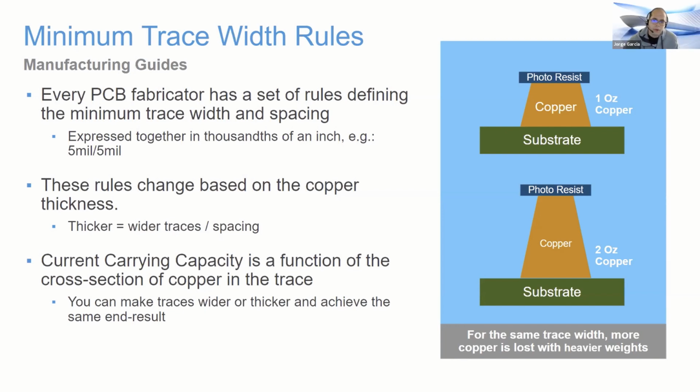Yeah, we have modeling for SPICE simulation, so you can calculate the currents, and there's also thermal simulation, so you could see how hot that copper would get. Like you mentioned, it is not ideal, because by having that extra length you have an additional impedance there, and then it becomes a parallel of two impedances. So one of them is going to draw more and heat up more than the other, and if you don't check that carefully, you may still blow a trace because of it.